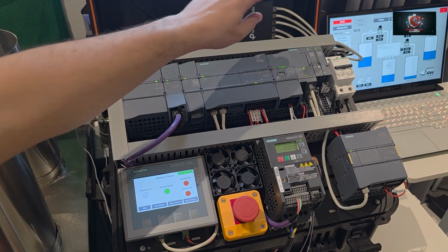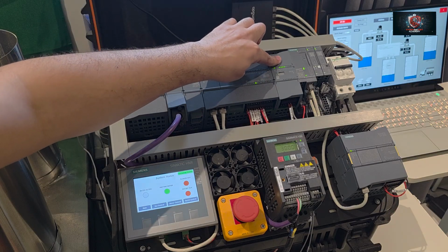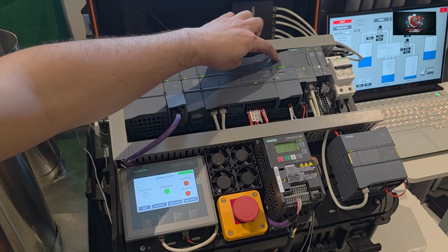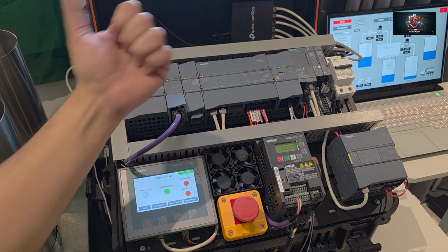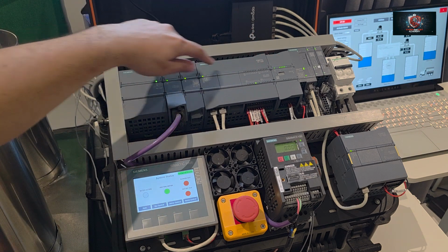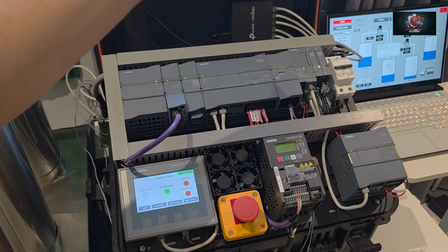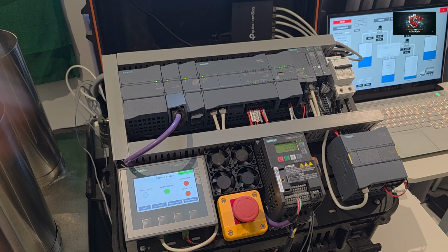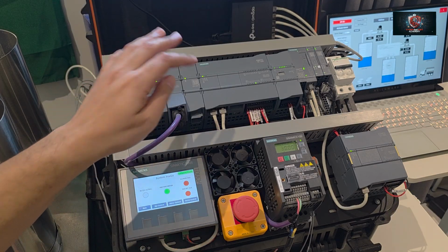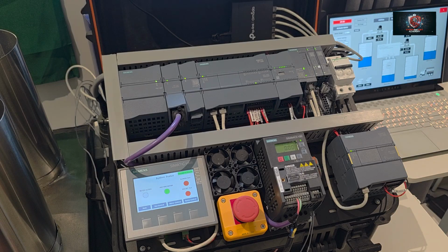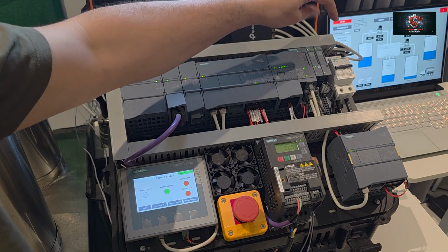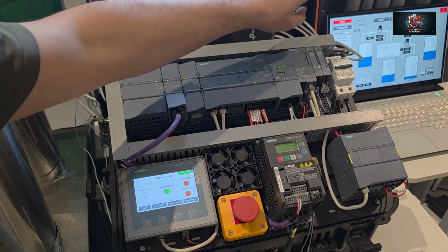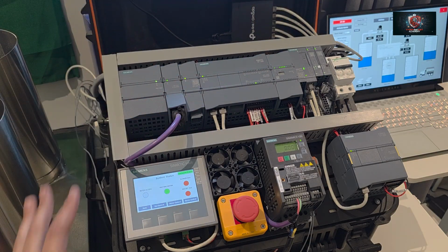Still under progress. I have here integrated the analog input card for the level transmitters in my tank farm. All this is set up in one rack. Of course, you can extend it based on your need as well. At the same time, it's one of the challenges when it comes to cybersecurity solutions like IDS. Again, making long story short, we have the remote IOs, and I'm only using digital input and digital output for remote IO. This is exactly what I need.